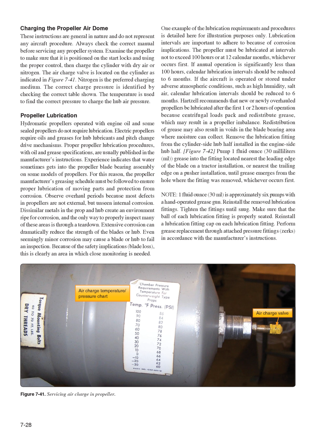Reinstall the removed lubrication fittings. Tighten the fittings until snug. Make sure that the ball of each lubrication fitting is properly seated. Reinstall a lubrication fitting cap on each lubrication fitting. Perform grease replacement through attached pressure fittings, zerks, in accordance with the manufacturer's instructions.